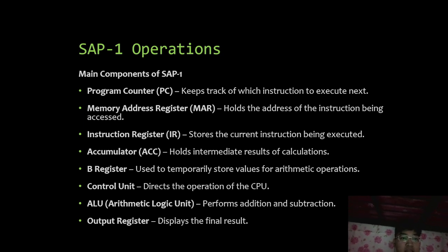SAP1 operation. Main components of SAP1. Program counter, or PC, keeps track of which instruction to execute next. Memory address register, or MAR, holds the address of the instruction being accessed. Instruction register, or IR, stores the current instruction being executed.